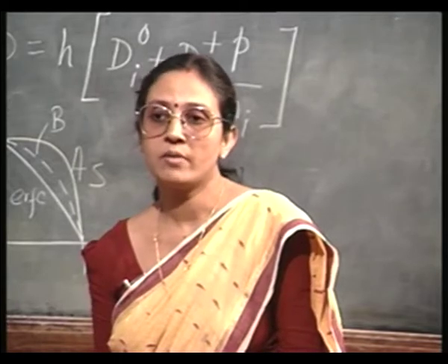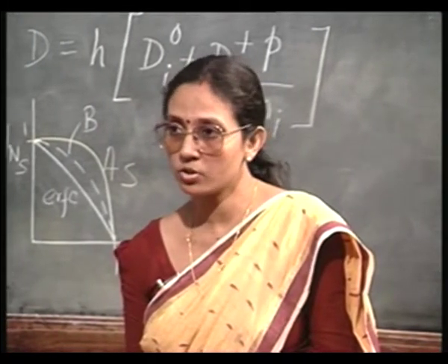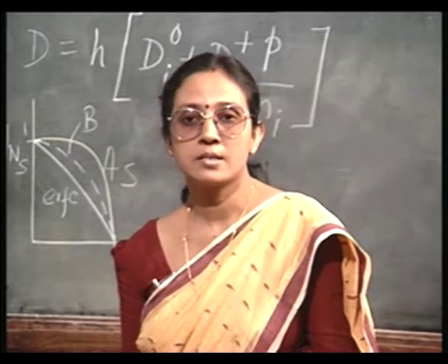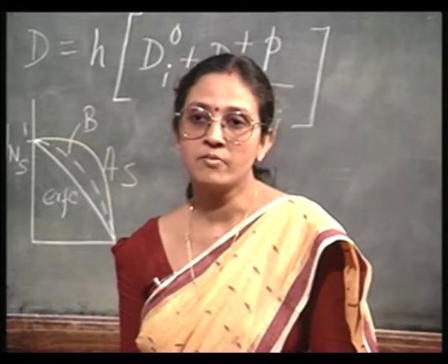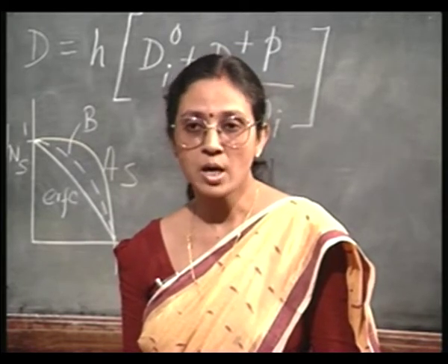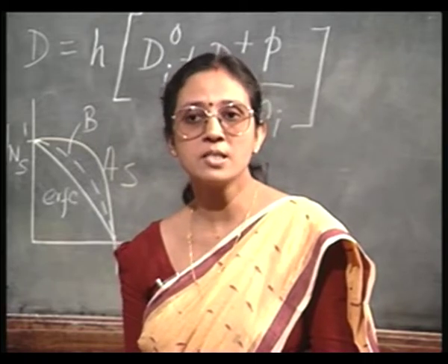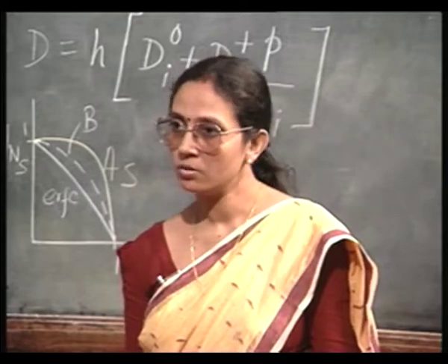You know, for a very highly doped semiconductor, Fermi level will be very close to the conduction band, and then for a moderately doped or for an intrinsic semiconductor, let us say, Fermi level will lie near the mid gap. Okay. So, as the doping concentration changes, Fermi level will move from close to the conduction band to the mid gap point.